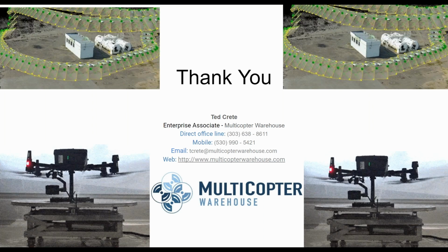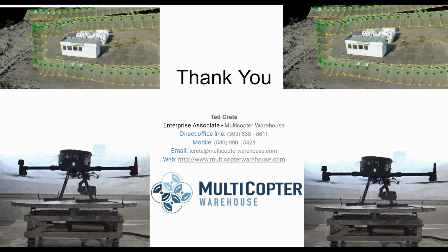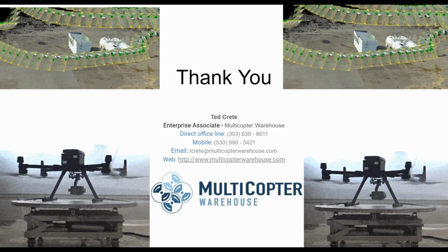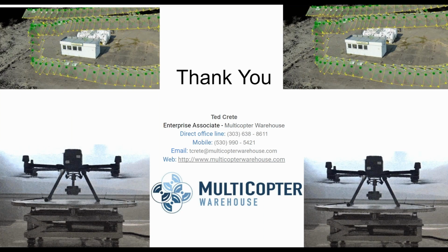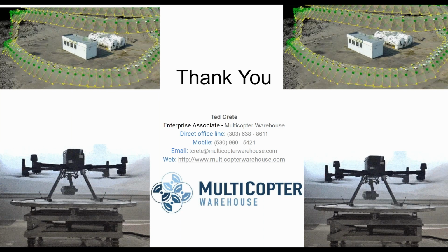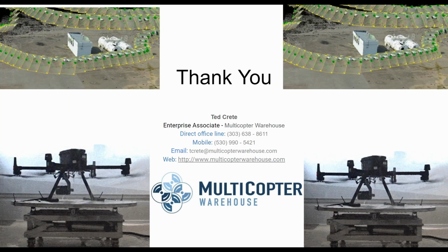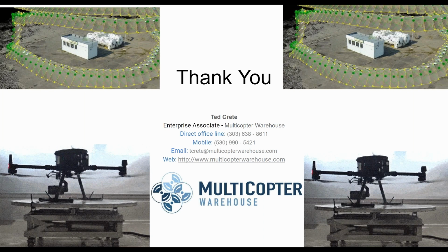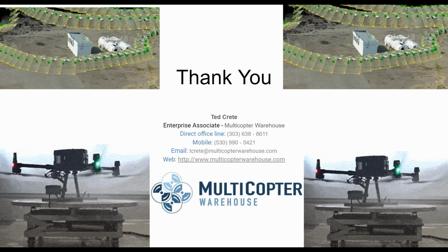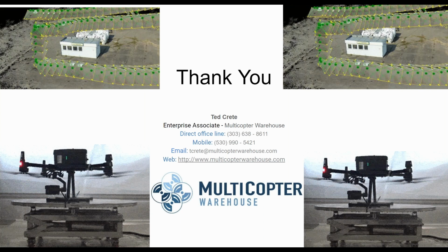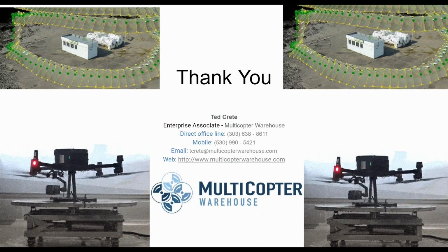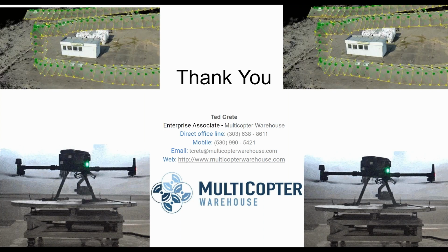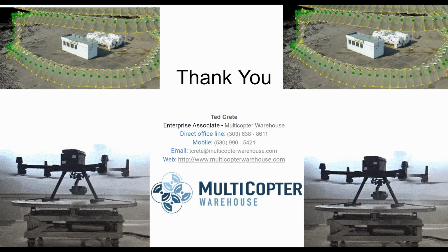Now, in practice, what I've seen is it gets pretty close to that, and after talking to several survey companies that use the DRTK2 in their workflows, they're getting about 3 to 4 centimeters horizontal and about 3 to 5 centimeters vertical with that raw RTK data. And then with the incorporation of 2-3 GCPs, you can make that as accurate as you would like, getting that sub-inch accuracy that most surveyors need.